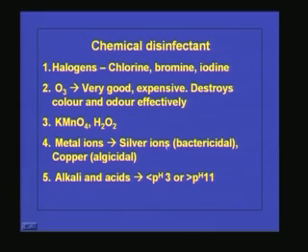In most of the water purifiers, the adsorbent or the activated carbon which is used for removing the turbidity, color and odor, will be coated with these silver ions to remove the pathogens. So, silver is being commonly used in such domestic water treatment units.